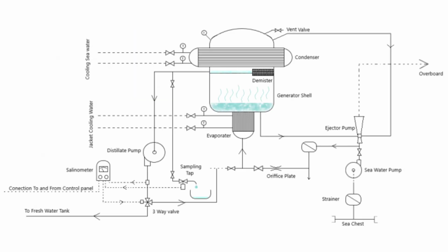Thermometers are installed for the control of seawater to the condenser and jacket cooling water to the evaporator. These thermometers permit control of both heating and cooling of these units. The salinometer or salinity indicator is connected to remote alarm so that very high salinity is immediately registered at the engine control room of the ship.